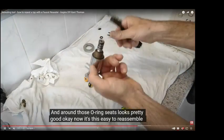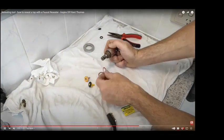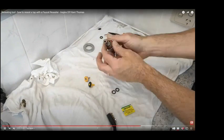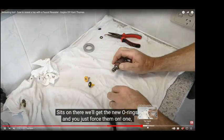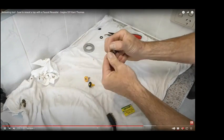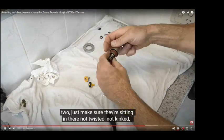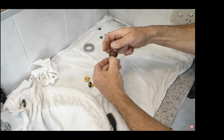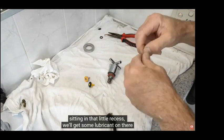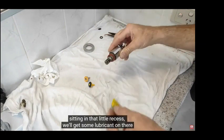It's probably too coarse. Too much damage. What he hasn't done is re-lube the spindle at all, so the tap is potentially still not going to run that smoothly. So he's going to stick the O-ring on. He's probably going to stick this crappy plastic jumper in there, which is probably going to give him more problems. Sometimes if you get water hammer with the tap, the water gets around the jumper and pushes down on the top of it, which causes it to smash or fire the washer closed, and then the pressure builds up, pushes it open, and it goes boom, boom, boom, boom, boom, right on that tap.